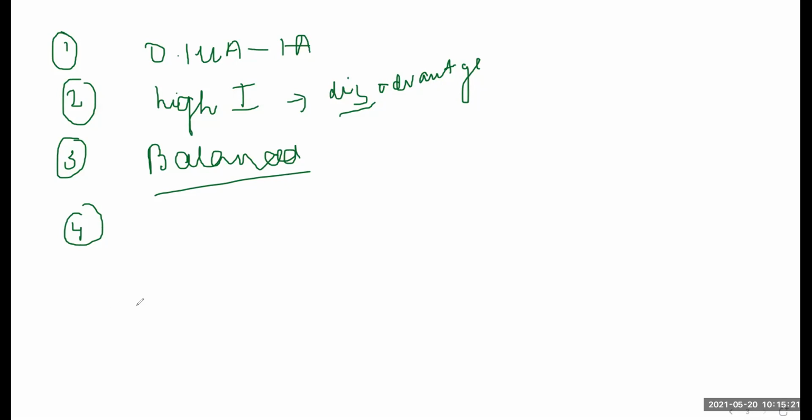Josna, are you there? Yes, ma'am. See, Kelvin double bridge is independent of load and contact resistance. So you need not think about what is the effect of load and contact resistance.